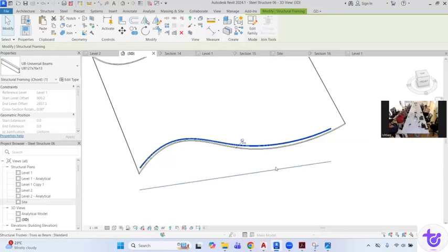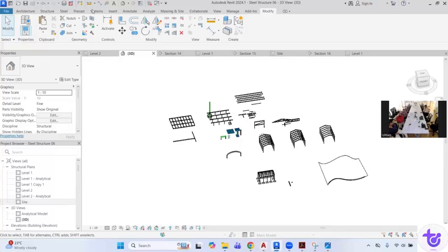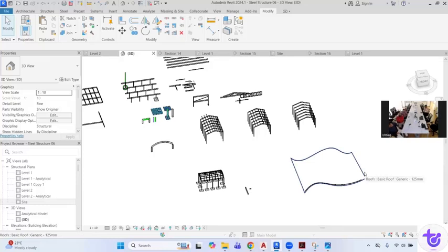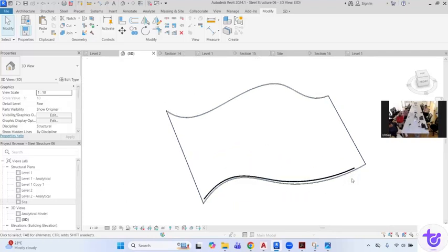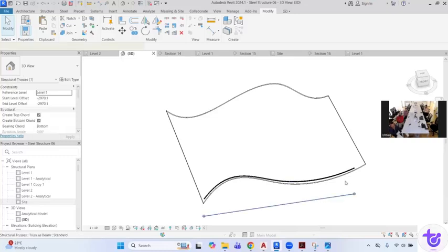One question: we are adding the roof as a curtain wall. We cannot manipulate the curtain wall profile. Actually, it is following the roof now. Whatever the category, it is following, because the attach and detach option is only available for floors and roofs. So the roof it can follow. If you have something else, then I think it may not follow. You can just go and try, but this is actually a trick.